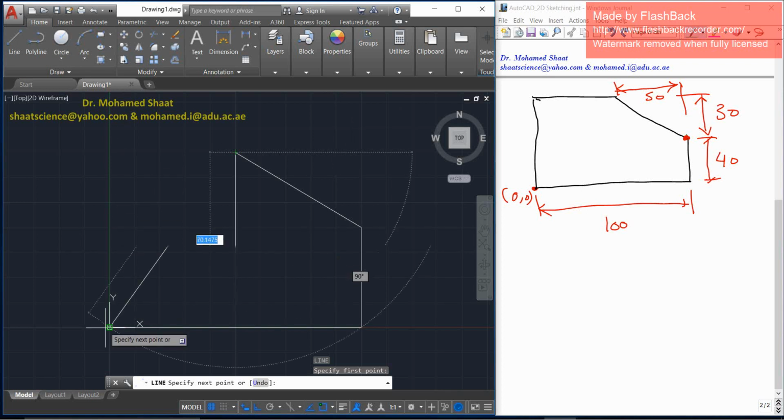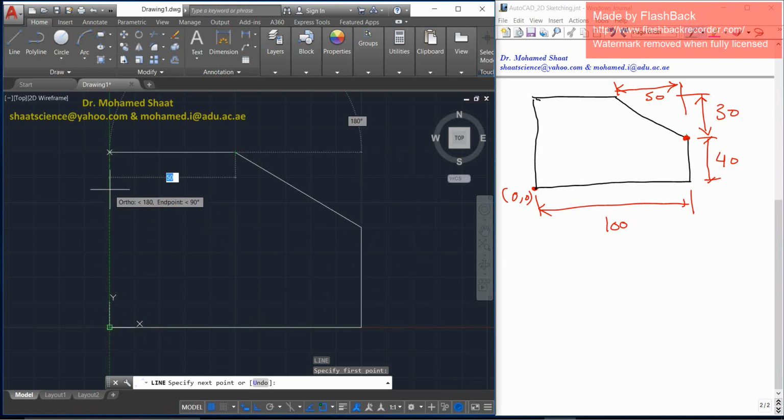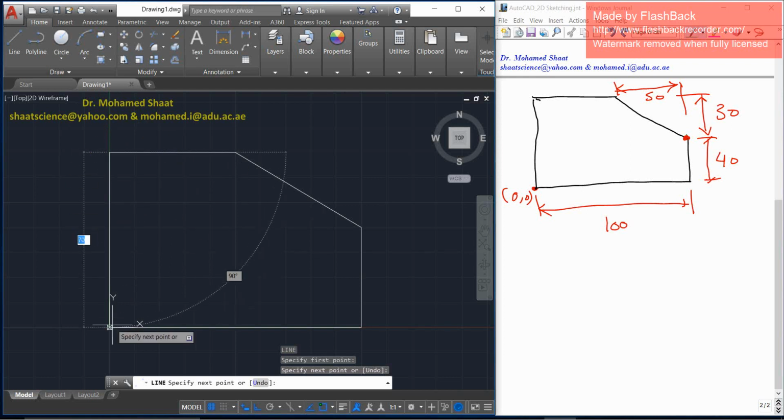Simply go to the point that you would like to extend from. If you go to this point and jump up again, you're going to see a vertical dashed line already shown, and there is an X point already located. If you just press here, you get the end point of this horizontal line typically above this point in the vertical direction.